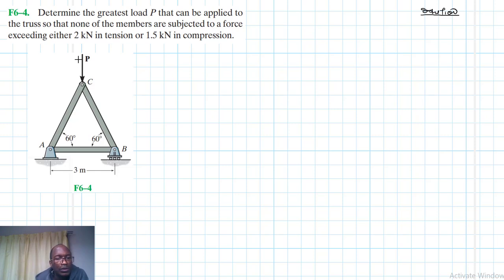So let's look at this particular truss. When we look at this truss, we realize that this is symmetrical about this axis, right? So the loading is symmetrical because even the reaction forces, you just expect the vertical reactions, the horizontal will be equal to 0. And the geometry also is symmetrical about that axis, and it makes the problem much easier.